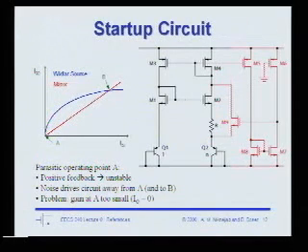So if we just use NPN transistors here, for the bottom Q1 and Q2, well, it shouldn't change, right? Because they're just diodes here. So if I use an NPN or PNP, it's a diode-connected transistor, so it doesn't really change anything. Then you can get rid of the cascode M1, M2, can operate with low voltage.